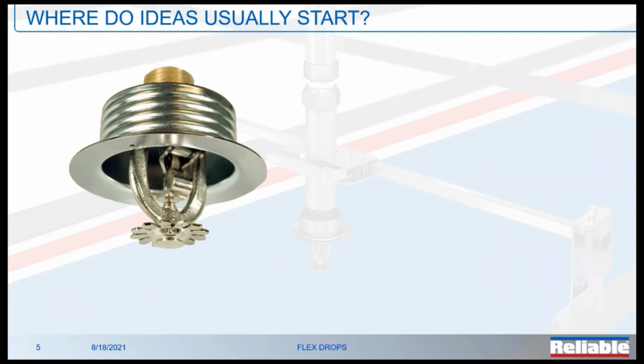And man, we struggled to put those in area density systems. Washington State, for instance, had a spec warehouse density, very popular, 0.39 over 5,600. San Diego, we used to do 0.33 over 3,000 as a spec warehouse density. So we didn't have a lot to choose from back then.